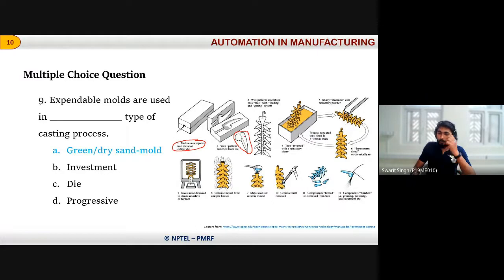We use investment casting for producing a larger number of components of the same type. These wax patterns are then attached into a tree-like structure, or a gate, that has a gating system and feeding system. This whole assembly is made up of wax.